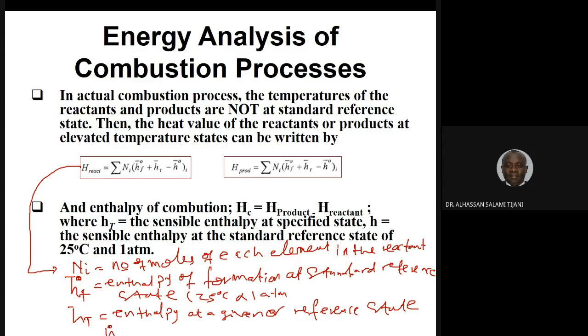And then the last one, H bar 0 equals specific enthalpy at standard reference state. So don't confuse this and this. This one is enthalpy of formation at standard reference state, and this is just enthalpy at standard reference state. All right, so don't get yourself confused with this.